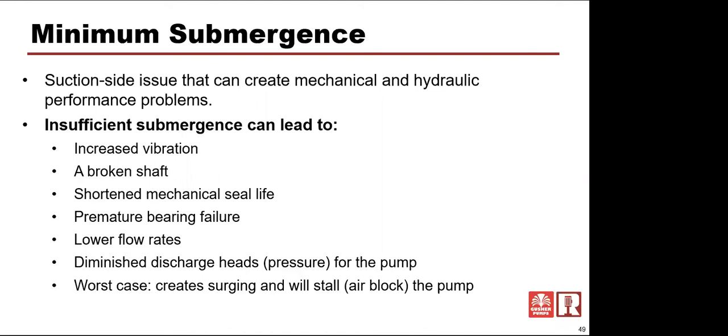They may be limited to 3, 4, or 5% air. Either way, whatever volume of air, it reduces the amount of flow, because that air takes up volume, and the pump performance falls different than what the curve says it'll do. Let's say 20% of that volume is air. Well, you're not measuring air in a system, you're measuring water or liquid flow. So a system that is 100 gallons a minute with 20% air, you're actually only getting 80 gallons per minute of water flow, because 20% of that is air.